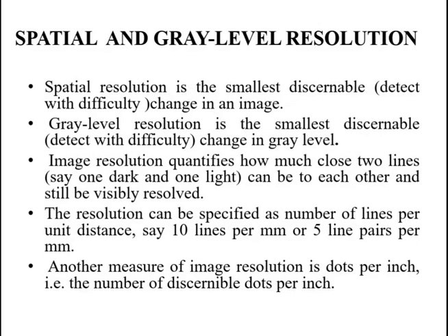Then the next one is gray level resolution. Gray level resolution is the smallest discernible change in the gray level. Image resolution quantifies how close two lines, say one dark and one light, can be to each other and still be visible, or resolved.